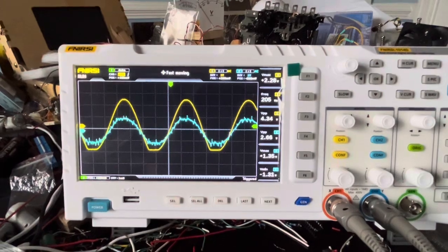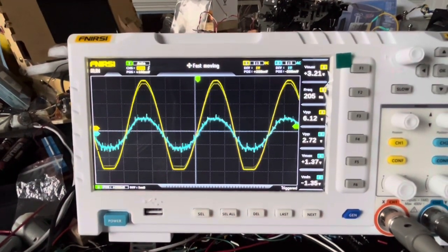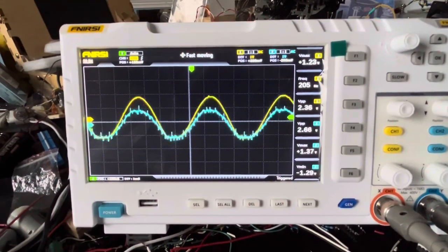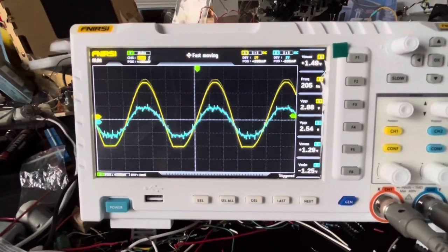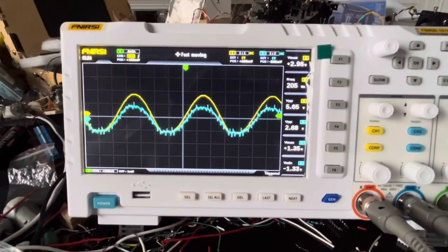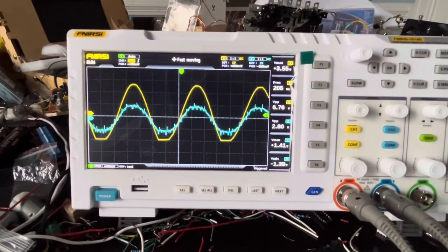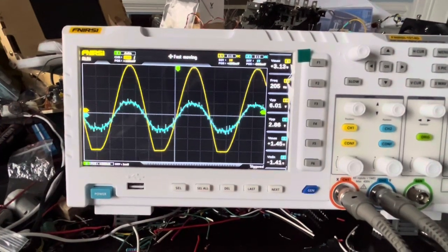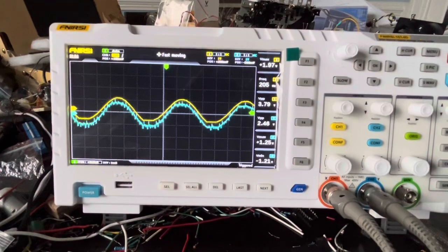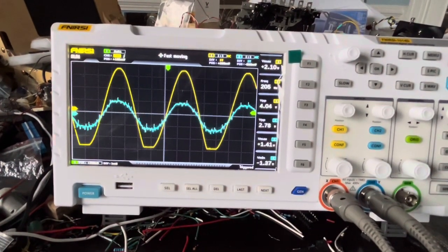Basically it's not going to go much beyond 2 volts peak to peak. So let's put it on the same scale now. Let me decrease it. Stays basically the same. So the compressor circuit decreases the dynamic range and finally gives me the holy grail of a semblance of automatic gain control of a signal. So I can keep a signal at whatever level I want, and it's not going to change around with the volume.